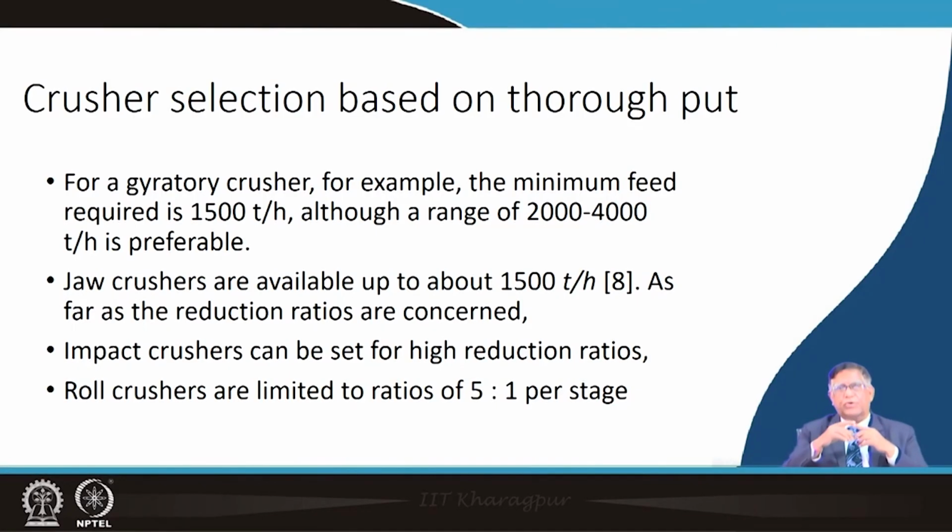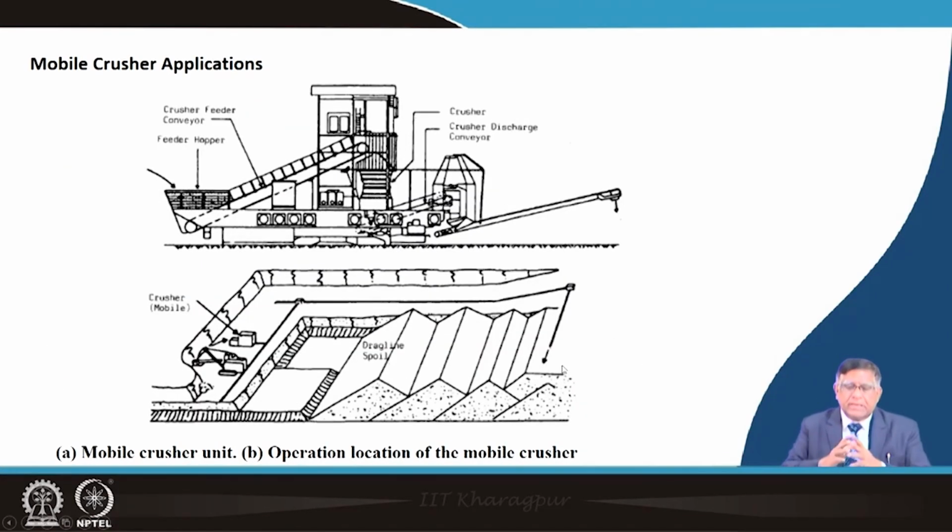You do not go for prescribing things tailor made for your requirement, which can be done, but it becomes costlier. Then how these are used as mobile crusher applications, you can see that this is a mobile crusher, there is a hopper, this is your crusher feeder, there it is getting crushed, and then the crushed material is again fed by this conveyor, and this is the discharge boom, and that whole thing is mounted so it can go.